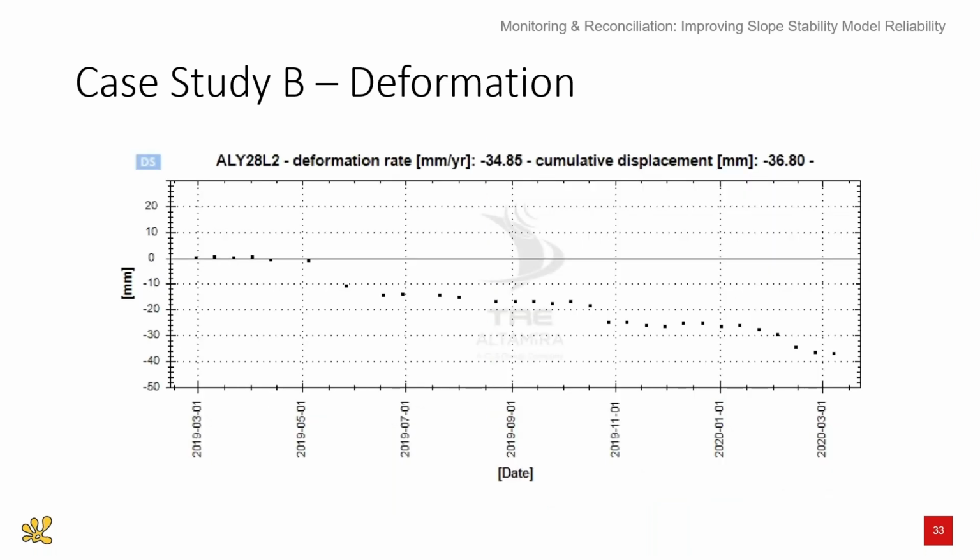And basically what that data, when you look at an individual point there, showed was changes in displacement rates coinciding with every time mining activities occurred near that south wall. So stick-slip behavior in alignment with mine progression.